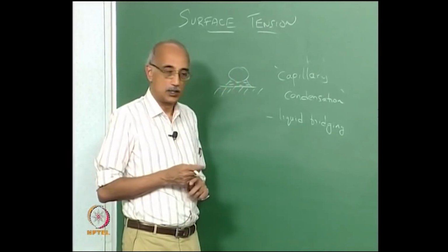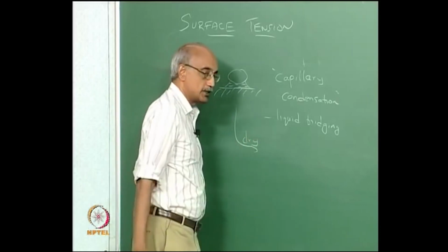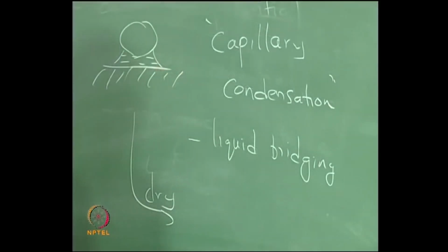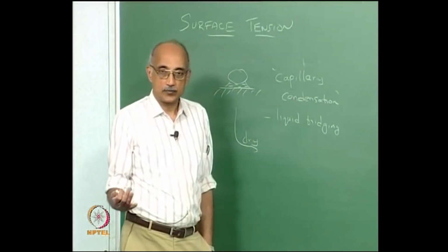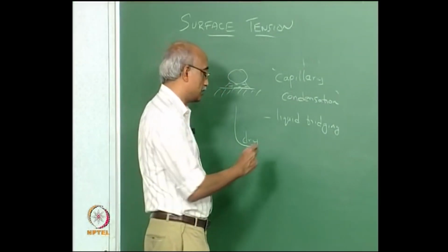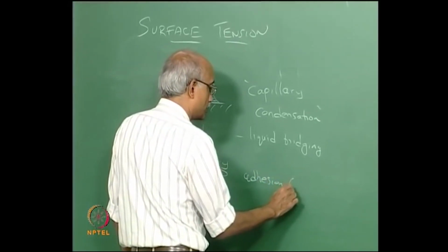the particles are still loose on the surface. Now, if you take this and you dry it, either just allow it to dry over time, or you actually provide active heating to convert this liquid bridge into a solid bridge, then the adhesion forces increase exponentially.